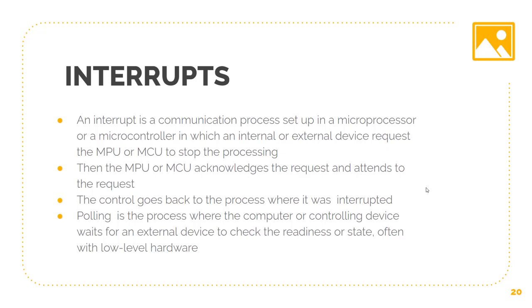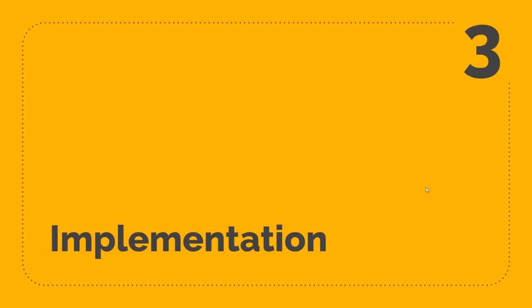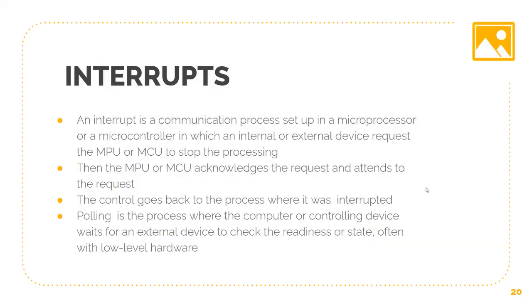We use interrupts here in our project to simulate the opening and closing of the door of the washing machine. In the board, we have three interrupts connected from switch 1 to switch 3. So basically RB0, RB1, and RB3.